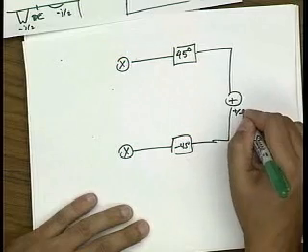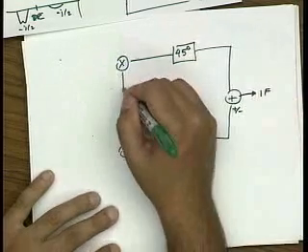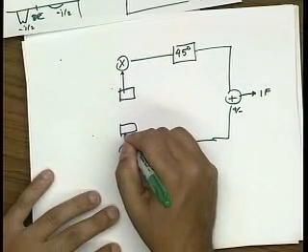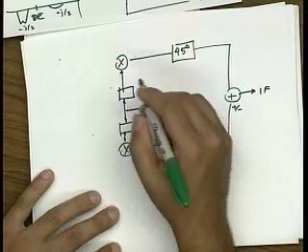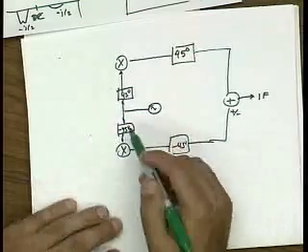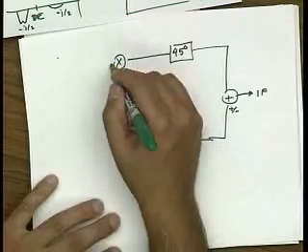This could be plus or minus depending on if it's upper side injection or lower side injection. And even for the LO itself, I can start out from a single LO, phase shift it by 45 degrees and minus 45 degrees. So this produces in phase and quadrature phase, I and Q.